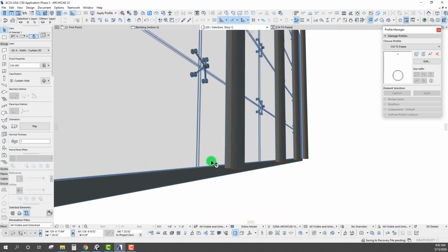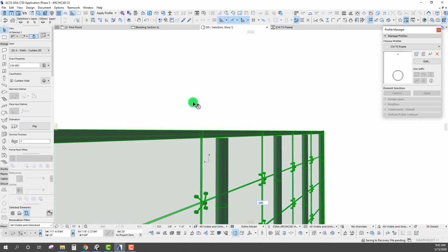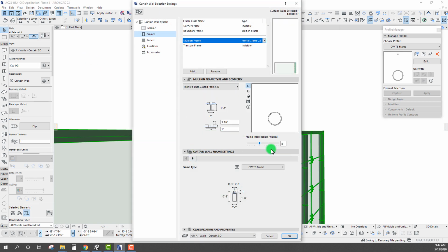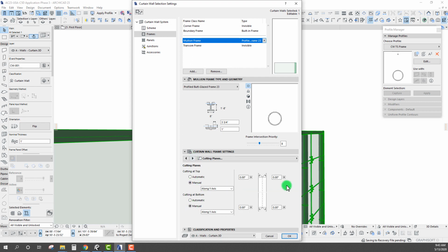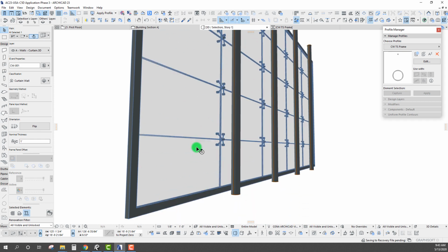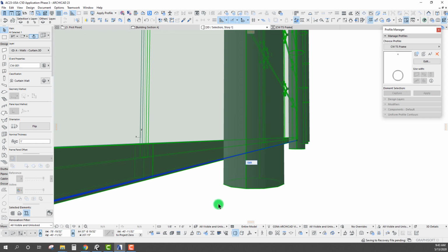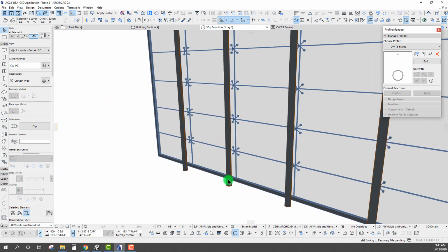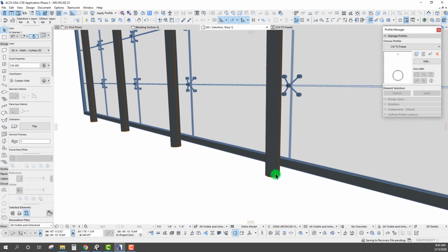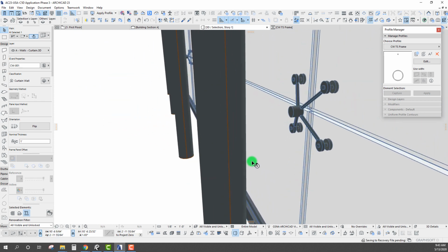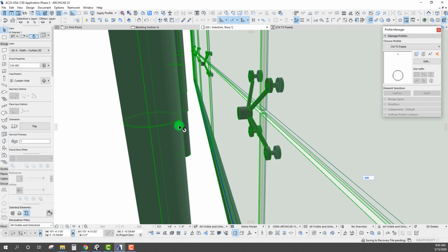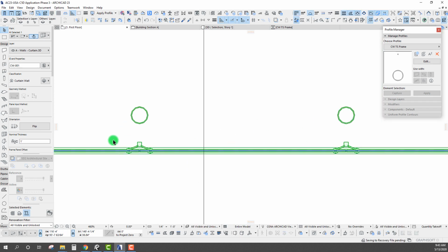So we can always add to this as well. Say if we wanted to make some adjustments on our cut lengths on those elements, we could go back in, and we have a setting here under our mullion frame to go in, and if we just set these to manual, it will actually go in and instead of cutting it at the frames, it's going to cut that at the overall boundary. So you'll notice that made these slight adjustments there. So all we would have to do there is just add like a base plate assembly to that particular tube steel frame.